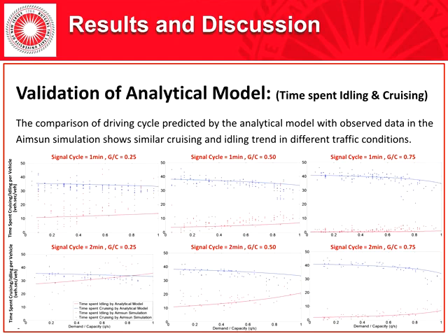They are compared with the results of simulation. As I said before, by reducing the capacity of the intersection with the signal timing, the chance of an oversaturated intersection increases, and it may cause more outliers in the simulation results.